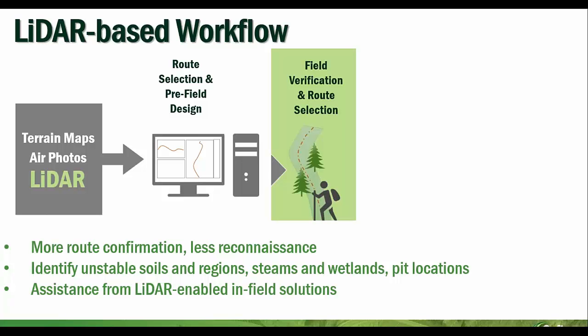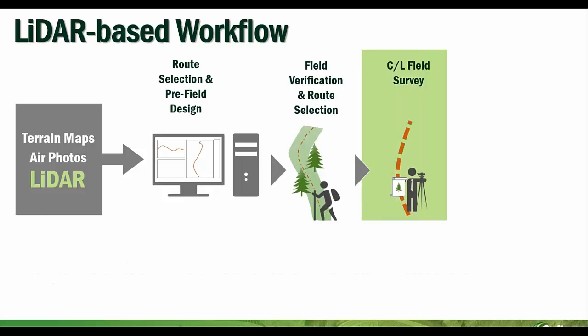And with this process, you can have assistance from LiDAR-enabled in-field solutions. For those of you who didn't know, RoadEng actually is able to run on Windows 10 tablets. So you can have your LiDAR data, all of your plans and profiles that you've developed in your planning phase, you can actually have them out in the field with you. From there, you're going to be doing your centerline field survey.